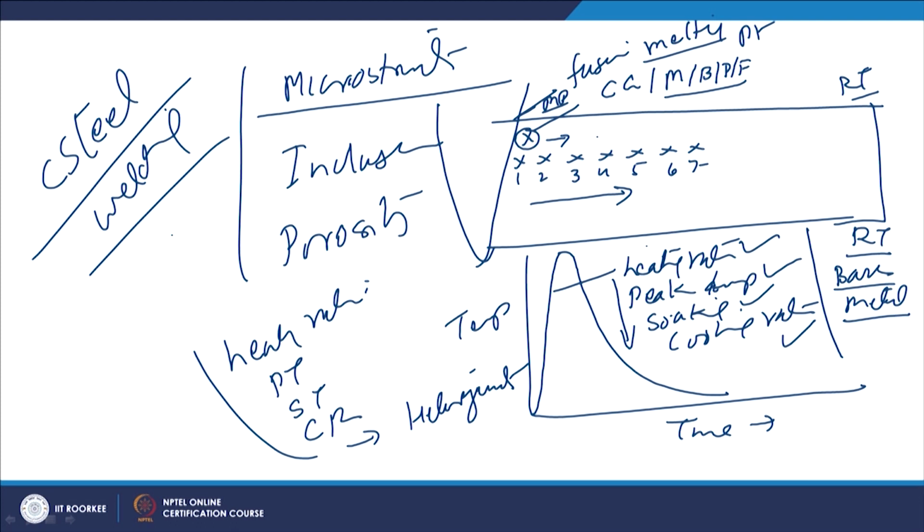On moving away, we get the fine grained HAZ, then the partially refined HAZ, and then the base metal. So, we may have very coarse grain martensite, and then fine grain martensite and ferrite mixture, and then a ferrite and pearlite mixture. So, the regions next to the fusion boundary will have a very heterogeneous microstructure, and accordingly the properties will change significantly, with very high hardness next to the fusion boundary and then reducing hardness away from the fusion boundary